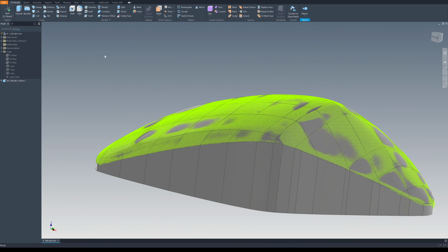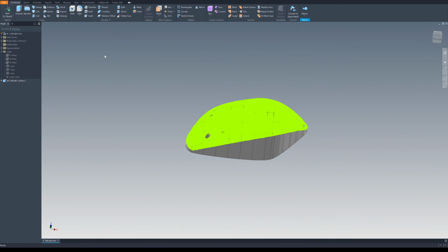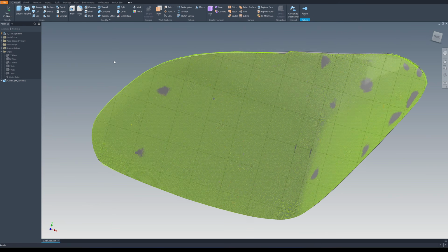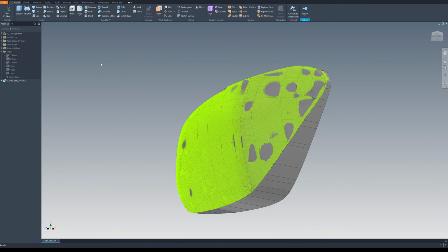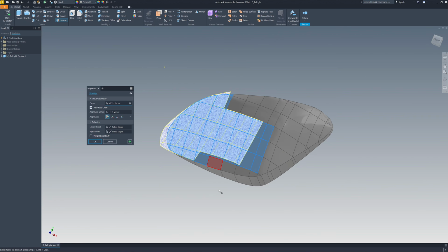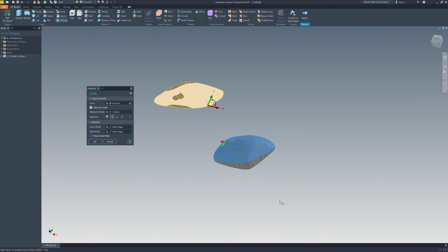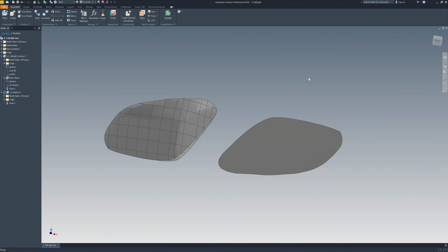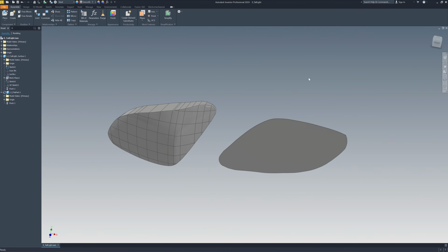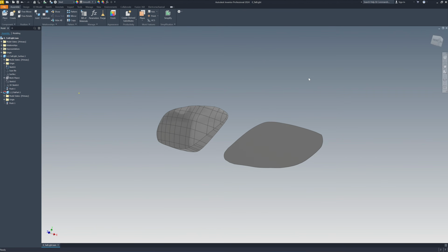If I use a smaller grid, the surface of the solid will match the point cloud even more, but it will take a longer time to create. This process took me about an hour to do. If I want a flat pattern for cutting the acrylic sheet for the forming process, I can use the unwrap command in Autodesk Inventor to create a flat pattern of this tail light, which is on the right. And after forming, it will fit into the 3D curve of the tail light.